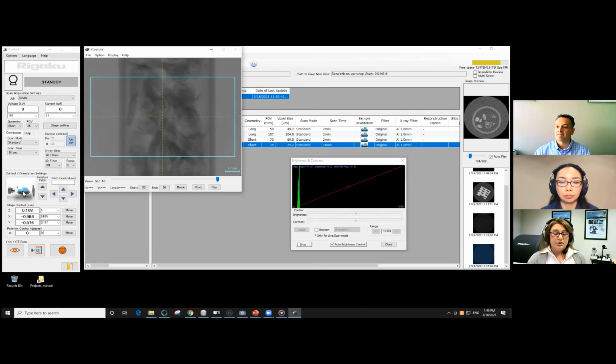Yeah, it's a good question. You certainly can, but your X-rays are still going through the whole thickness of the material. So a lot of them are being absorbed. Ideally, your field of view and sample size should be closely matched. But if you don't have the choice in cutting or trimming the sample, then you can do that. It's going to require longer measurements. You may have some other undesired effects, but you can do it.